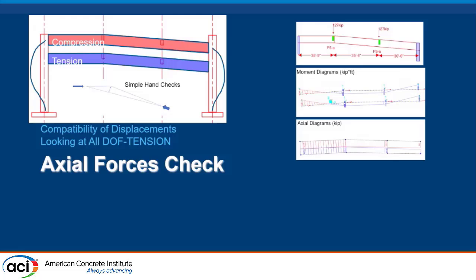Another, maybe from the same project, was a column with two large girders. The girders that I was mentioning were in torsion, and this is the one exaggerated display shape. What we found here is the compatibility of deformations created some Vierendeel type action. We were getting high compression in the top and high tension in the bottom. It explains some cracking we saw in the field.